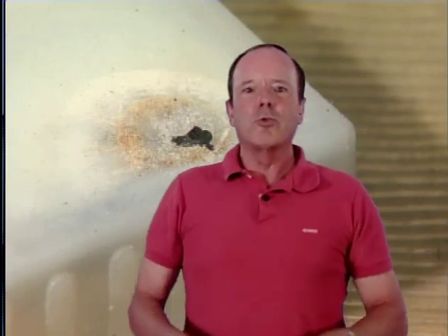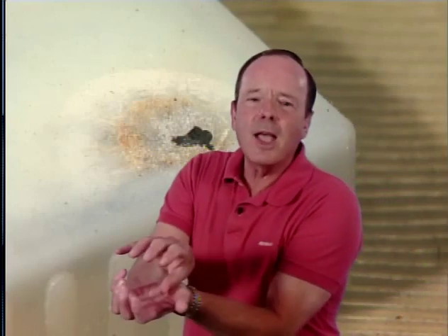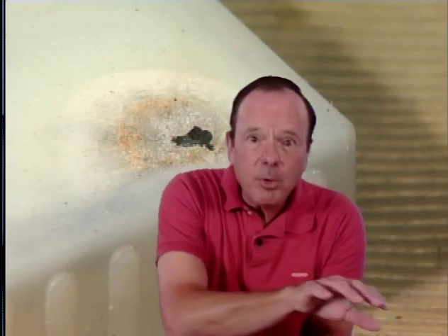First of all, NiCad batteries tend to heat up when current moves either into them or out of them. So let's assume that you've really discharged the NiCad battery. Say you had a difficult engine start, and now you're charging that battery back up. Well, it'll tend to heat up the battery when you charge it back up. Now, NiCad batteries have low internal resistance, so that allows a very high rate of charging current, and that, of course, heats up the battery further as you charge it. So you discharge it, it heats up the battery. You charge it, it heats up the battery.